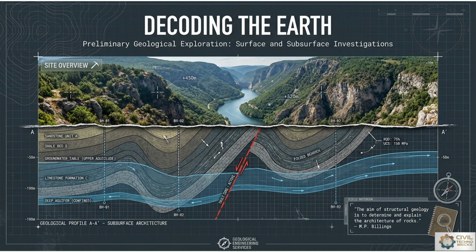This information is extremely important because underground conditions directly affect foundation performance and structural safety. Therefore, geological subsurface investigation is one of the most important stages in civil engineering planning and design.